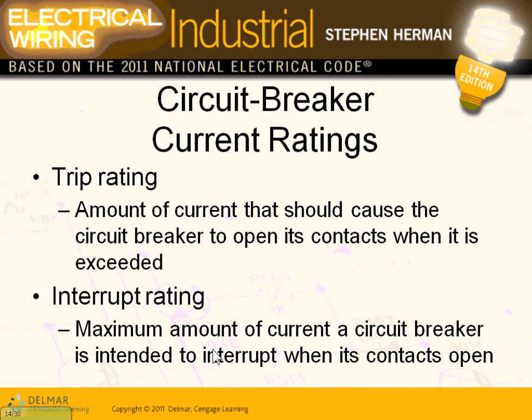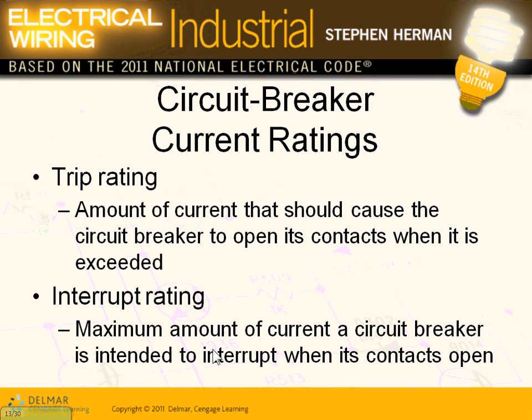Any question about this? Any question? So these are your circuit breakers, your electronics. So we have the thermomagnetic, 99% of the time, well, 80% of the time we're going to do thermomagnetic. Only when you start having 1000 amp or higher does it start making sense to have an electronic circuit breaker. I'll give you guys a break in a second here.